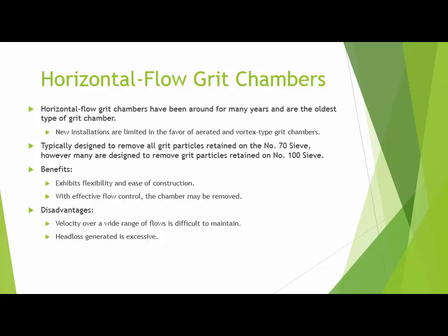They're being limited now in newer treatment plants because of the use of the aerated and vortex style grit chambers. They're typically designed to remove all the grit particles retained on the number 70 sieve, for those of you who are familiar with soil mechanics and being in the laboratory. However, many of them are designed now to remove grit particles retained on the number 100 sieve.